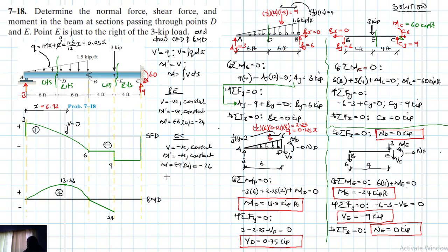Okay, so moment finally at C is equal to the algebraic sum of minus 24 minus 36, which is minus 60. So the slope is negative and constant, so just expect a line like that, and that value there we said is minus 60, which we just put like that.